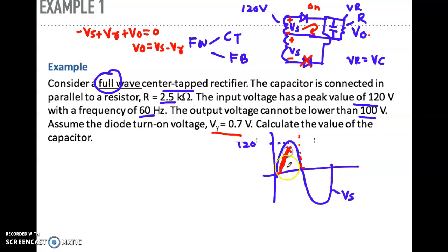Okay. So once it reaches the maximum voltage, this means the capacitor will be charged. Meaning the diode will be on, and your capacitor will be charged. Okay, once your voltage starts to decrease, that's where the diode will be off, right? So when the diode is off, the capacitor will slowly discharge, until it reaches the second positive cycle, then it will be charged again.